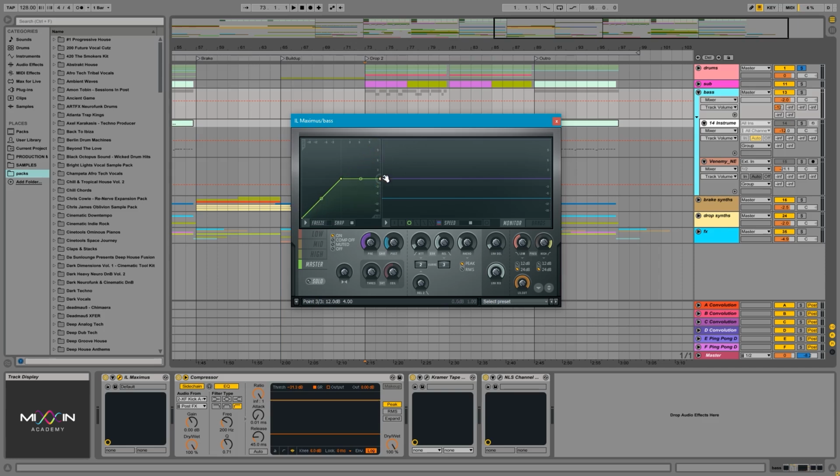If I did this, any sound louder than this limit right here would get limited. So if I go in, let's say -3, goes out -3, go in -1, goes out -1. But if I go over that point, so let's say that on the input, I come in with a +3 volume, so over this line, it would still go out as 0. So any value above 0 would go out as 0, since I'm limiting at that value.